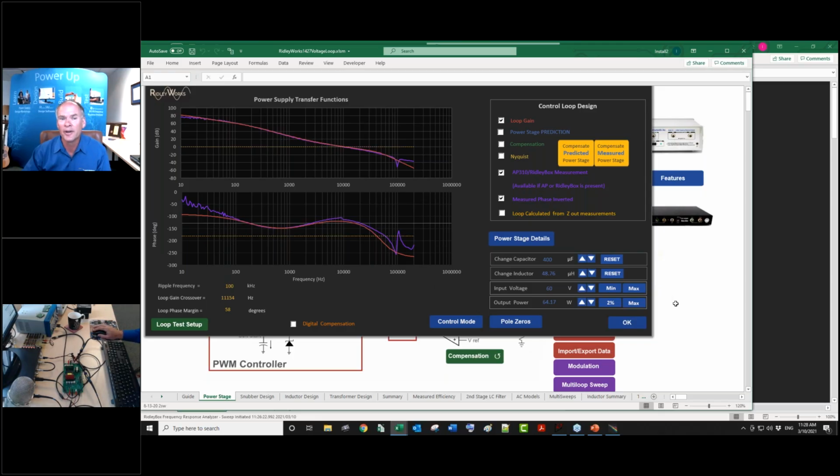It's just not true. Now, if you have a right half plane pole in it, so the system is open loop unstable, then you get a different situation where the Bode plot is not going to give you the right answer, or you have to read it differently. But I don't think I've ever seen a power converter that naturally has a right half plane pole in it. So I don't think we have that.